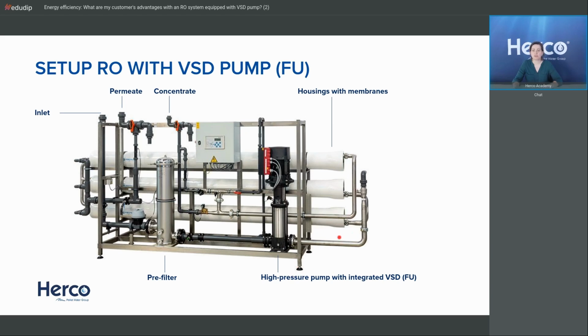And you see here, you don't have a throttle valve anymore. So what happens here at the startup is that the flow rate after the pump is measured automatically by the unit. This gives a 4 to 20 milliampere signal to the switchboard, and the switchboard adjusts the variable speed drive so that the pump is running exactly at the speed percentage that corresponds to the proper flow rate. So the advantage is also that you don't have to set anything, you don't have to adjust. It is automatically running at the right point. It also runs at the right point if operating conditions change. There's no need to readjust later.